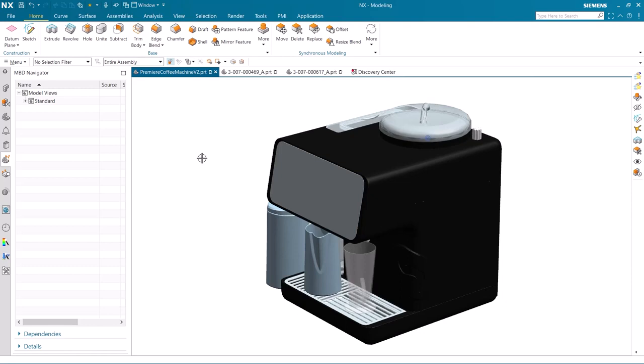In a single part, I added a rule to display the PMI of the holes in the part. We noted that the MBD rule efficiently and smartly selected, added, and grouped associative PMI information to those holes, with hole size and tolerances for each specific hole. The MBD rule utilized a tolerance lookup table that greatly assisted in defining the use tolerances for each hole, and is based on hole size. This removes the need for manually adding tolerances to each hole.